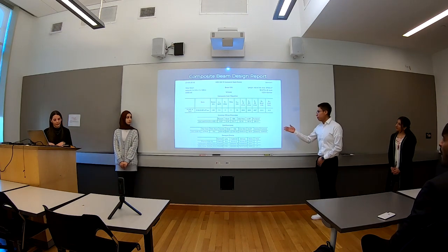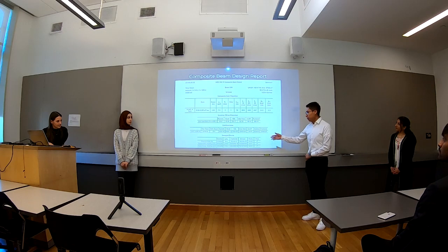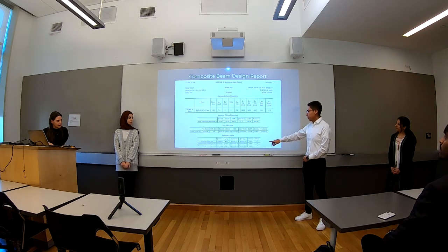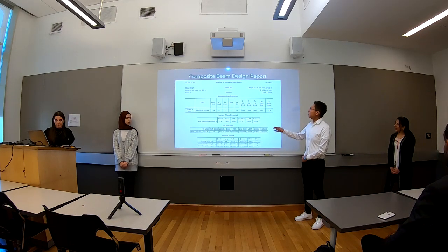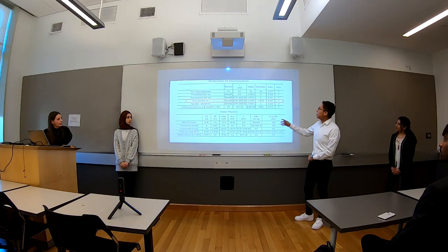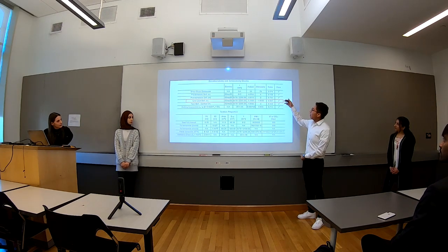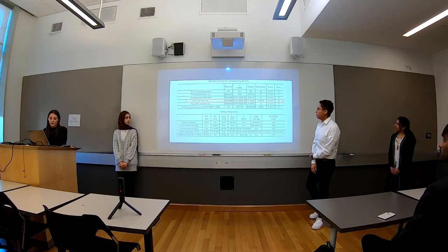And this is a report that was provided by ETABS, where it essentially calculates based on the design loads, the shear was satisfied, as well as the construction bending moment and partial bendings. They're all satisfied. And this is for W18 by 40. As well as right here, it shows that the allowable, everything were satisfied based on the selection.